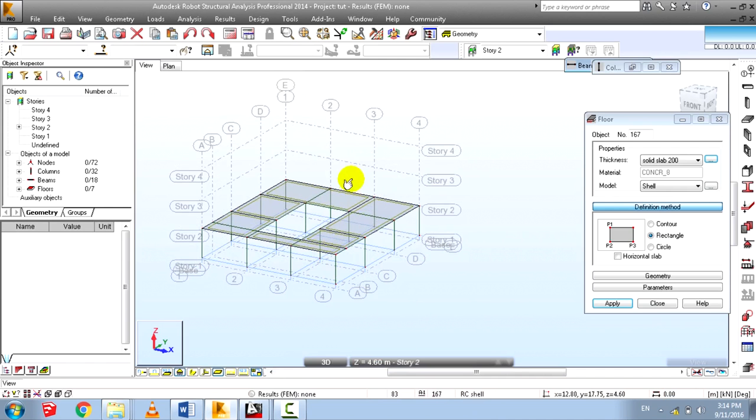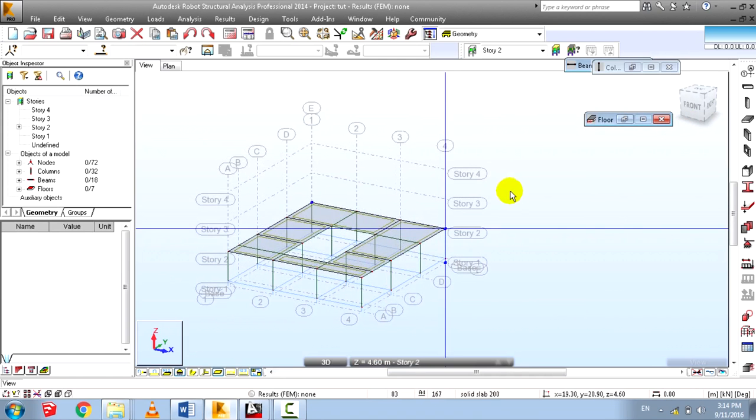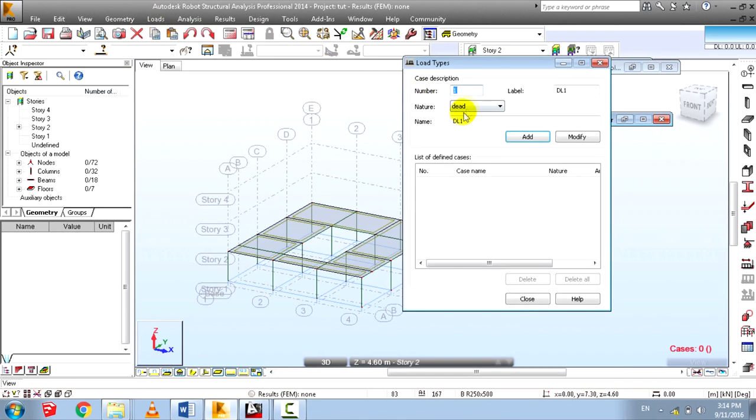And the best thing we can do right now is introduce the loads right here. As soon as we introduce the loads right here, it will be as simple as that. We can just make a dead load just like that, and then just let me get a live load. Just make sure it's LL1. Okay, just make an add. I'm just not good with the dead load. My dead load should be different from the actual dead load, so I can just make an add. Let's close it up.